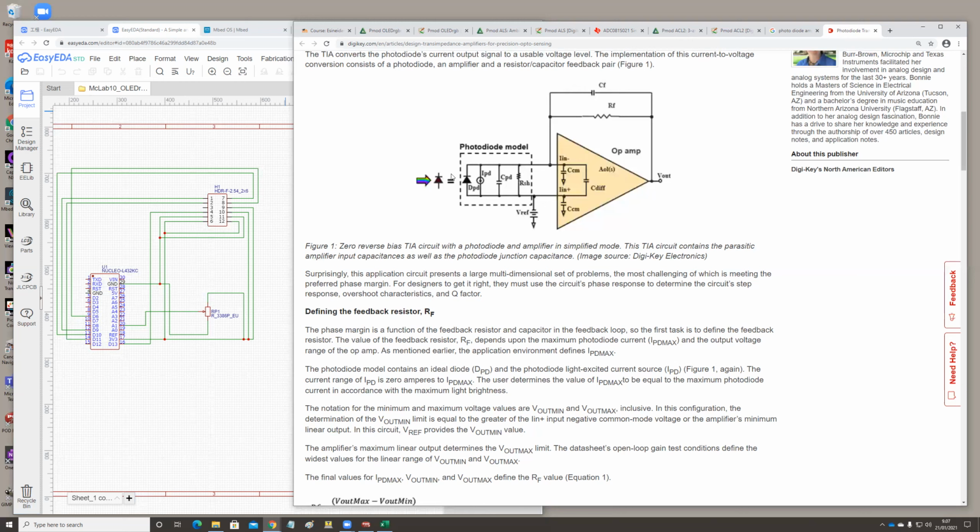The photodiodes are used, for example, in communication technology, so in receivers of the fiber optics channels. So when you have a fiber optic link in a data communication, the receiver is quite often a photodiode. And then you put a really small capacitor here, and you get the fast changing bits of the transmission through this amplification and through the input of the next circuit.